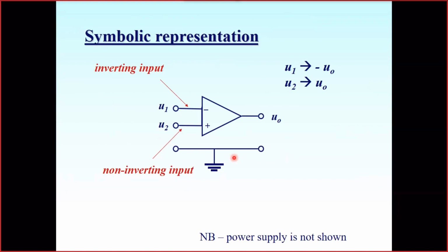Of course, and actually, what this device is doing. It has two inputs. One of the inputs is named the inverting input, the other, as you understand, is non-inverting. In the circuit drawings, the non-inverting input may be marked with a plus. Usually the inverting input is marked with a minus, but sometimes only the non-inverting input is marked with a plus. If we know where the non-inverting input is, the second is automatically the inverting one.